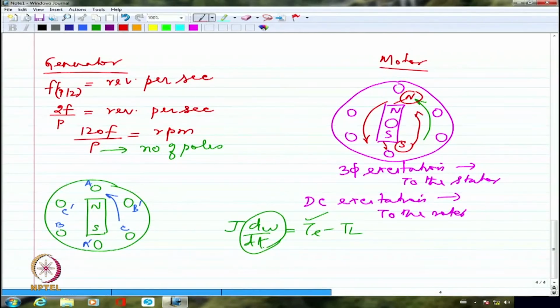If at all you look at the rotor of a synchronous motor, if you start off with 50 Hertz right away, you are going to see that the rotor will not be able to catch up with the revolving magnetic field speed right away, because of which there will be only attraction and repulsion alternately taking place, and that is going to actually make a dwindling motion only, if at all you see.